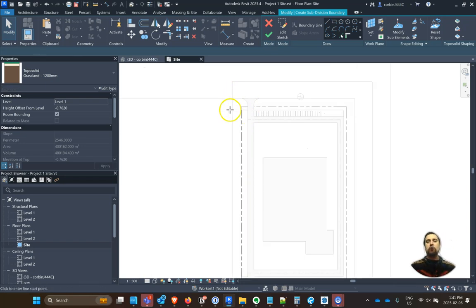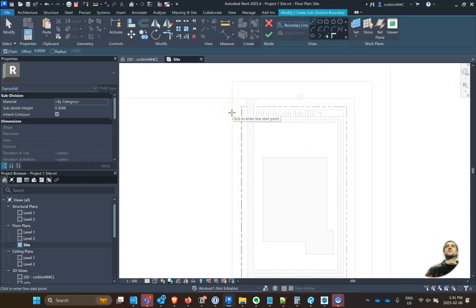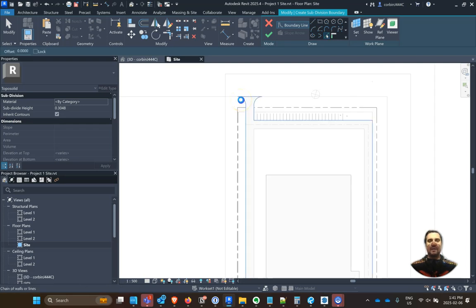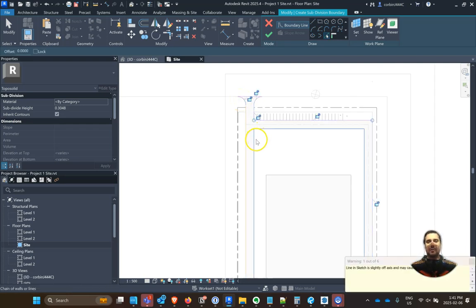This time I'm going to do my roads. You can obviously notice my roads are based on the feasibility study roads. I haven't really updated them, but it's the same concept. So we're just going to use the pick line button again. We're going to click this, and we'll click this inner one.